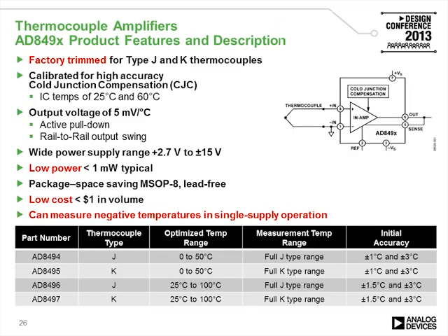We've done that with a series of thermocouple amplifiers, our AD849X, which includes a high accuracy instrumentation amplifier as well as the cold junction compensation. Runs at very low power so that the self-heating does not induce errors. It's a fairly low cost device and works over a fairly wide temperature range, and these are quite popular.